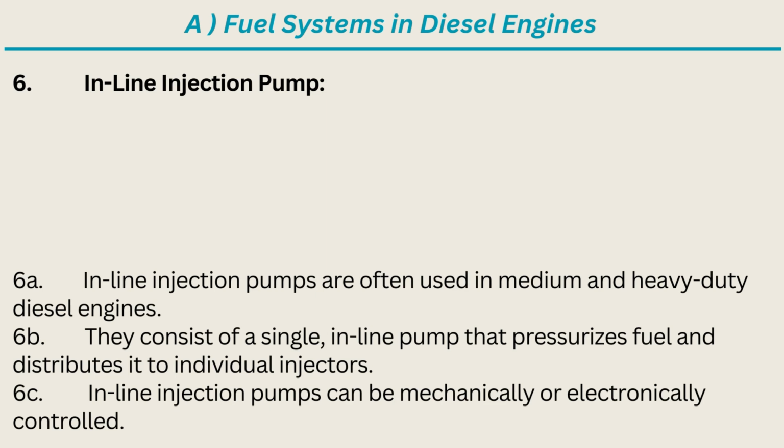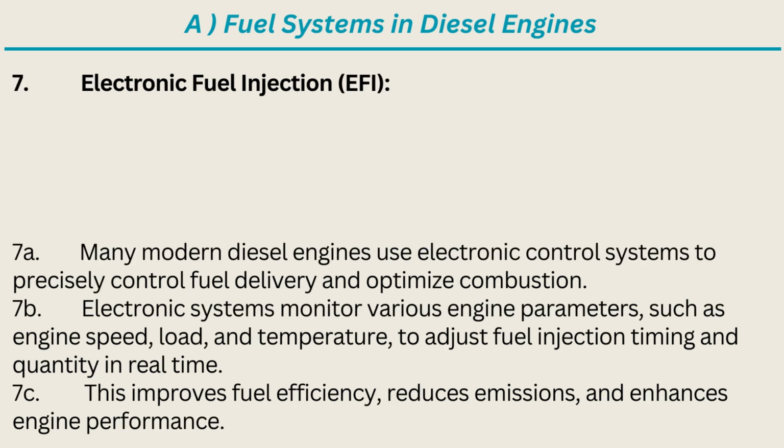6. Inline injection pump. 6A. Inline injection pumps are often used in medium and heavy-duty diesel engines. 6B. They consist of a single, inline pump that pressurizes fuel and distributes it to individual injectors. 6C. Inline injection pumps can be mechanically or electronically controlled. 7. Electronic fuel injection, EFI.